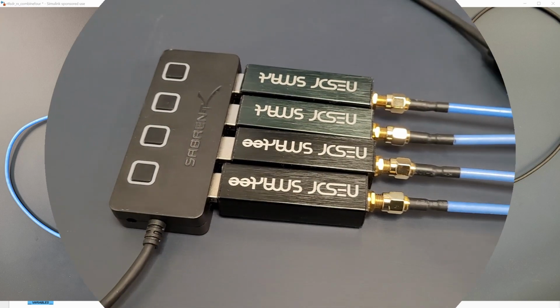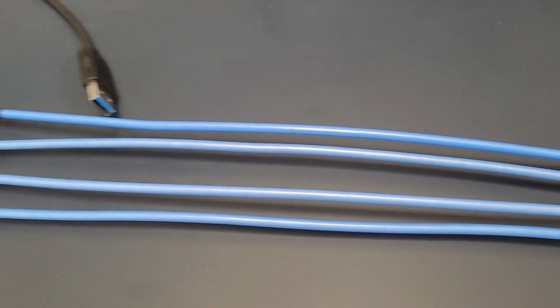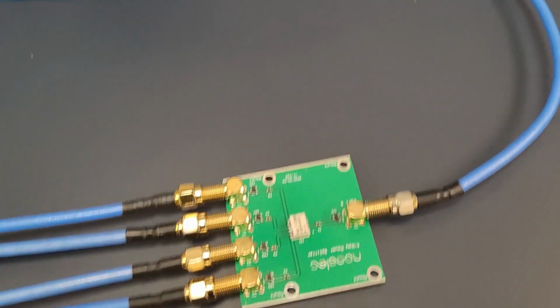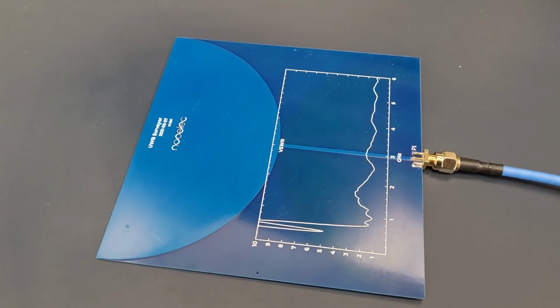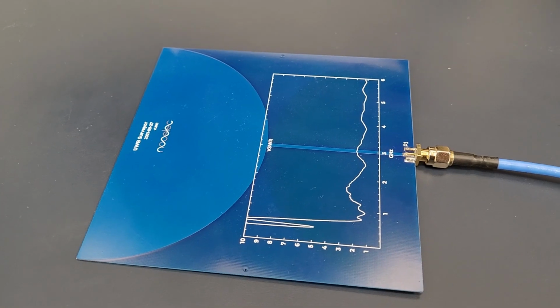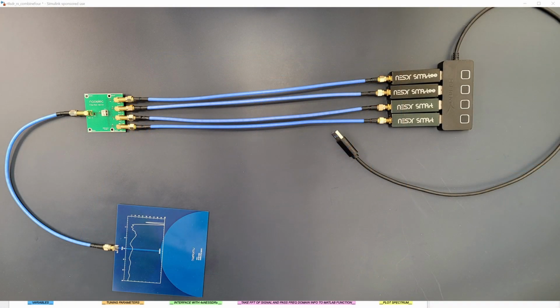We have 4 SDRs plugged into a USB 3 hub, and each is connected to one of the 4 inputs of a splitter or combiner, and an ultra-wideband antenna front end to help us survey the spectrum. Now, if you ensure you have a USB 3 hub and connect it to a USB 3 port, you'll be able to power all SDRs simultaneously without issues, since the power is supposed to be sufficient.